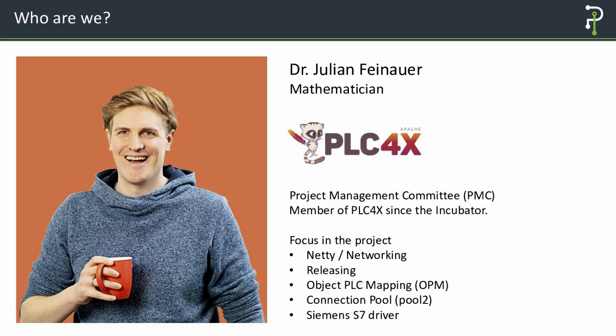I wrote a module, Object PLC Mapping, OPM, which is a bit like JPA. So you have POJOs where the getter magically makes a call to the PLC, really a bit like JPA if you know it. I wrote a new connection pool implementation, and I worked a bit on the Siemens driver. So this is the stuff where I have really deep knowledge, because a big part of the code is written by myself.